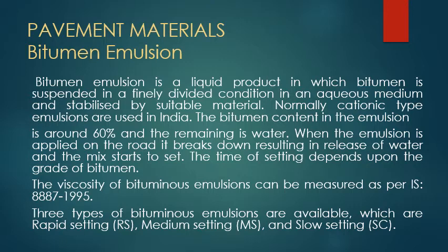The viscosity of ordinary paving grade of bitumen varies considerably with the temperature, resulting in bituminous pavement surface courses being susceptible to temperature changes. Means during hot weather the bituminous pavement surface courses become soft, and during cold weather it becomes too stiff and brittle, with the possibility of early cracking.